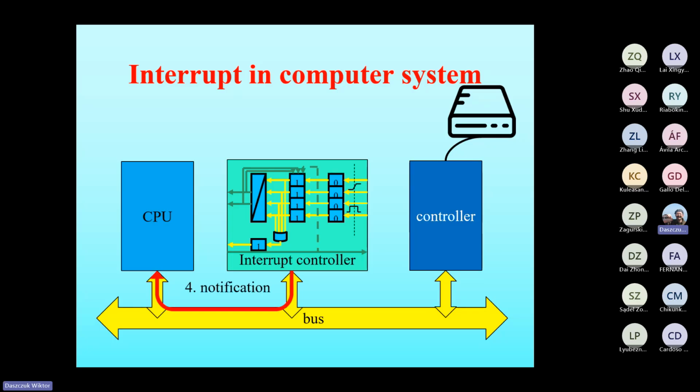When the controller decides to send the interrupt to CPU, it is a single interrupt line. No, not one out of many. It is a single interrupt line, and it sends the specification of this interrupt when CPU sends the acknowledgement: I am ready to accept this interrupt.